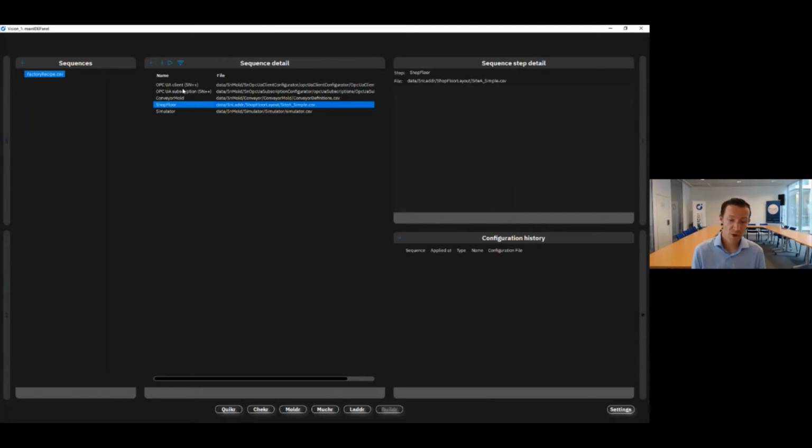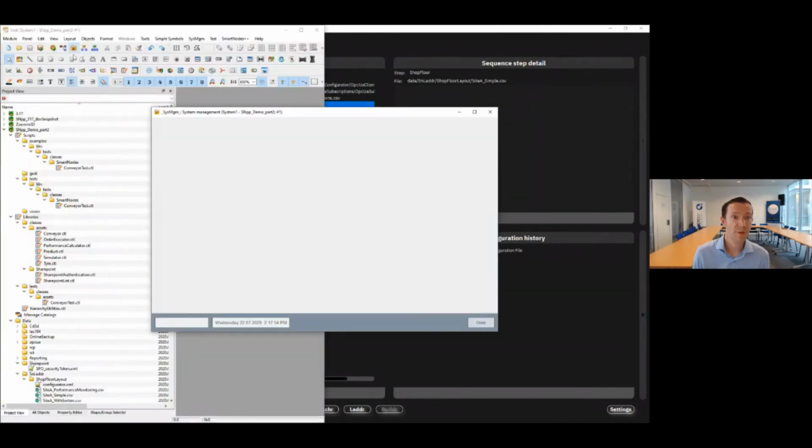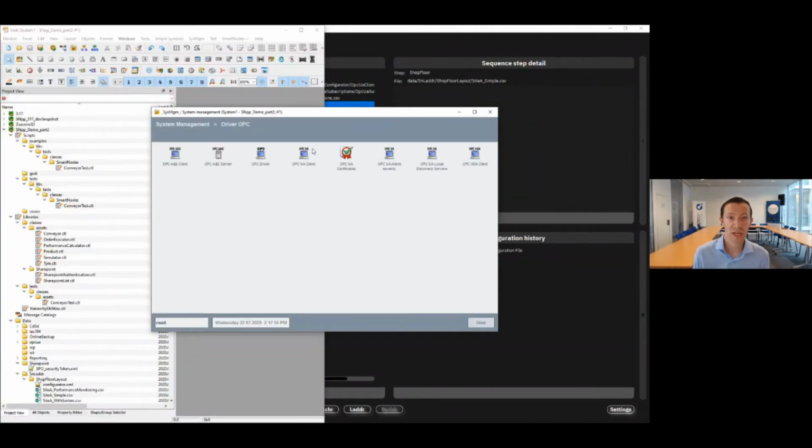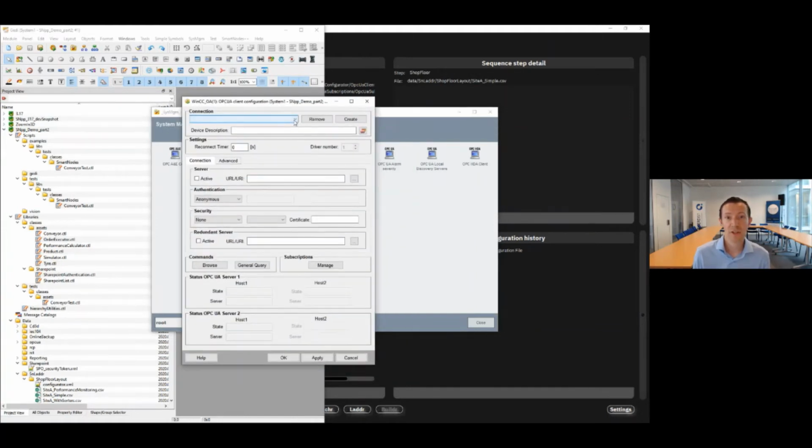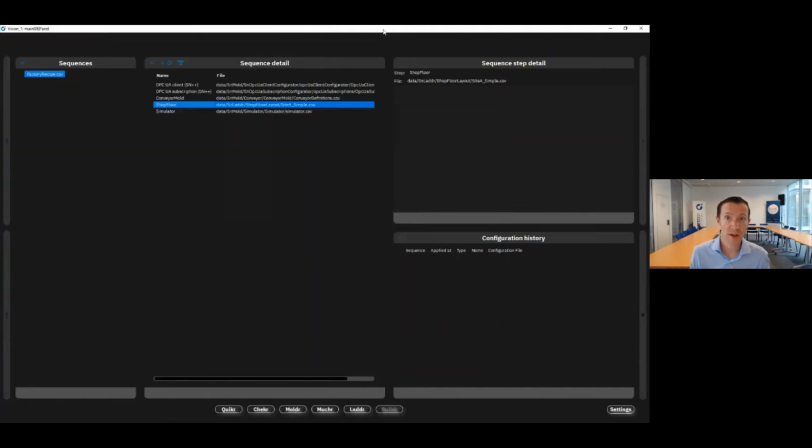So when you go to the system management to create OPC UA information here, OPC UA client, you see in my project this is currently empty, but we will need one of these because our conveyors, we are reading them out with OPC UA. So this mold that I have here is going to create the OPC client, and this will create an OPC subscription. And I've also got the simulator, which is the simulator that we needed to simulate the behavior of the items on the conveyor belt.